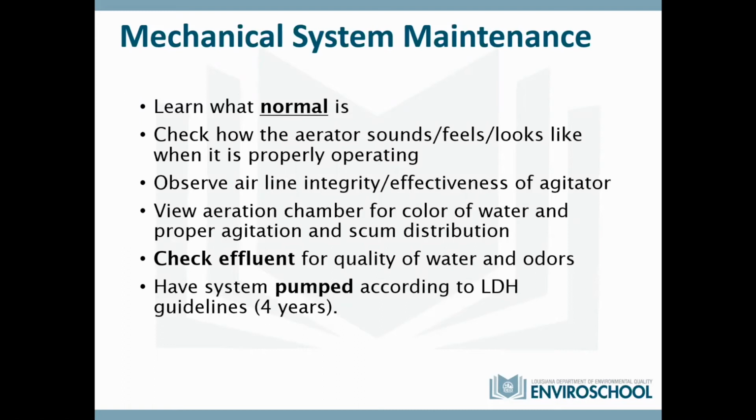Periodically look in that chamber to make sure that there's agitation, that the water is being disturbed. And again, you want to see the color of the water. What I was told and what I've seen is an earthy tone with an earthy smell. Make sure you don't have scum building up, like a lot of grease trapped on the top of the aeration chamber. That shouldn't be going on.